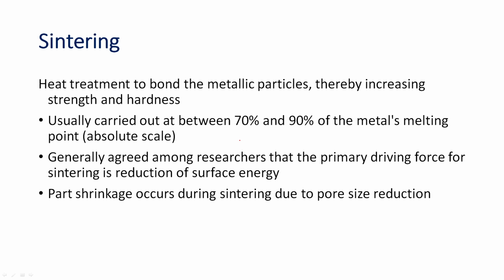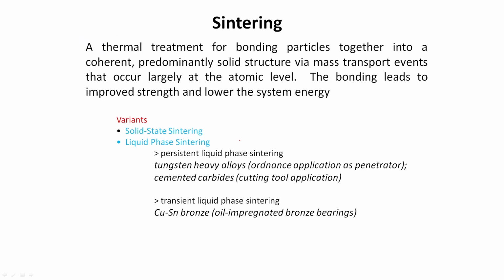The particles will connect to each other, and that is how they reduce the surface energy. This will lead to shrinkage, and that is the way you can measure that the pore size is getting reduced. From a layman's point of view, this is a thermal treatment for bonding particles together into a coherent, predominantly solid structure by mass transport or diffusion that occurs largely at the atomic level, and bonding leads to improved strength with a lower system energy.